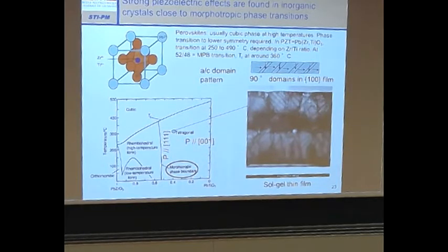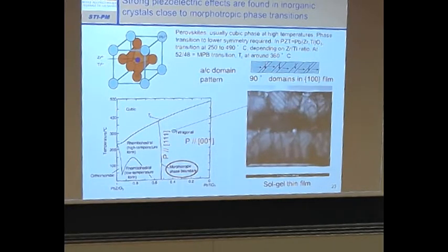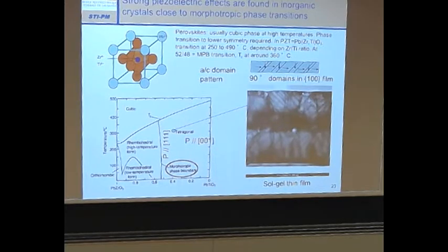That's why you cannot freely say, well, I would like to have only C orientation. You can do that on specific substrates. Unfortunately, this is normally not silicon. But on specific ones, of course, you can use strontium titanate or lanthanum aluminate substrates. That's one of the complications you have to think about in your work.